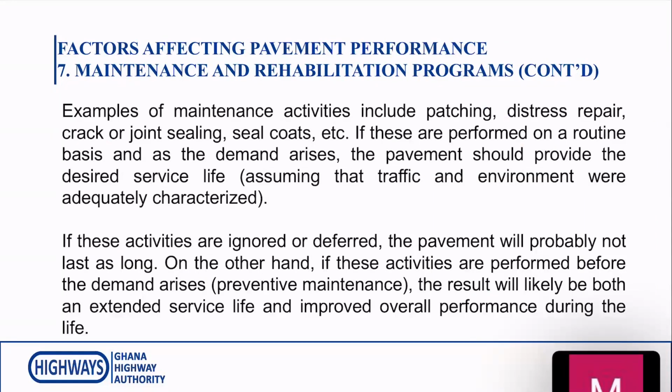Examples of maintenance activities include patching, that's pothole patching, crack repair, joint sealing, and seal coats, etc. If these are performed on a routine basis and as the demand arises, the pavement should provide a desired service life, assuming that traffic and environment were adequately characterized.